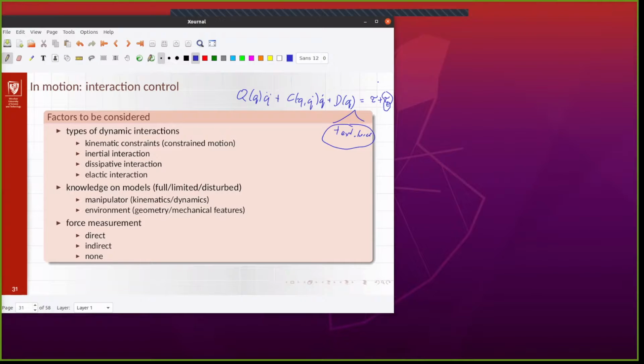So you can use that property for indirect force measurement. When you have, let's say, a compensator of the movement, you keep the manipulator stable, someone adds some external force to it, and to keep it stable again, you need to apply increased torques to the robot.